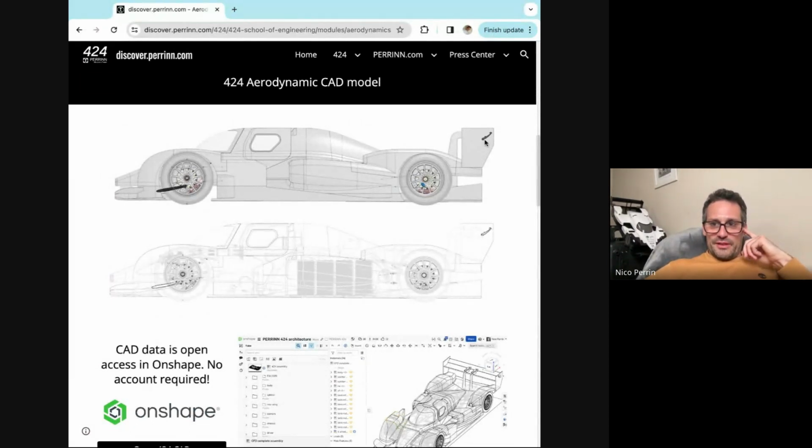So when we open the flap at the rear, then the flap at the front drops. The hinge point is at the front, and the flap drops. So we reduce the drag by about 30%. The downforce reduces by about 25%. And we also reduce the front downforce to keep the car balanced.